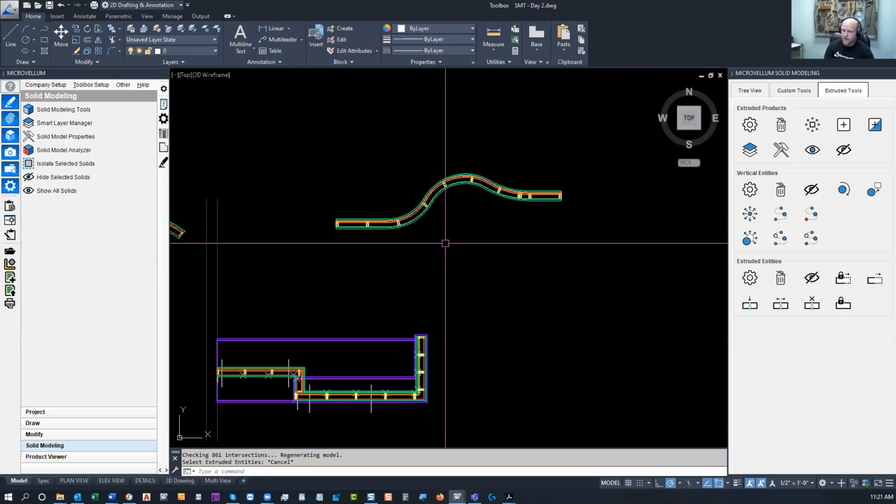The company I came from, when we did any kind of curved walls, we did stacked layers of MDF. Depending on how tight the radius was, we'd either use 1/4 inch or 1/8 inch, kind of a door skin. And we just found we got a lot better product using the MDF versus a bending ply or curved core. It just held its form a lot more fluidly as we went through these products.